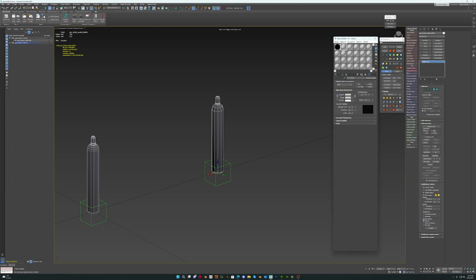Start a new material, call this LOD 1. We'll go into the diffuse map, the maps, and all we'll do now is drag over the LOD 1 texture, put it in the diffuse, and the LOD1.mr and put it into the specular level. Then we'll go into it and change those to UV channel 2. So all LODs are always UV channel 2.